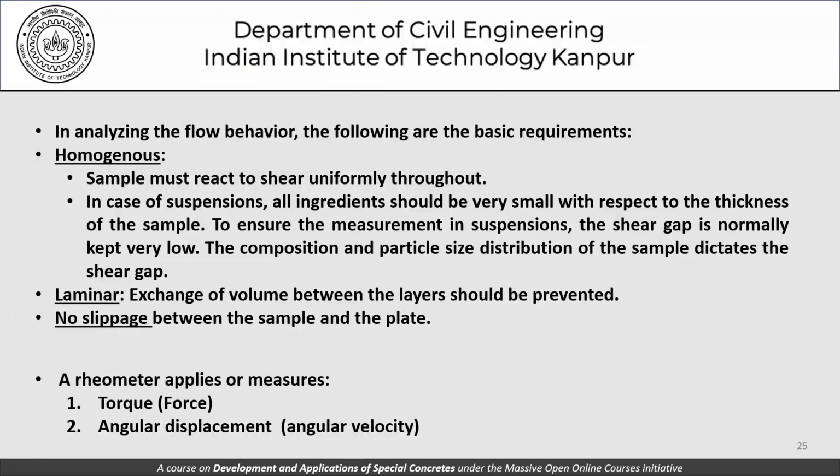In analyzing the flow behavior in concretes, or for that matter any fluid, the following are the basic requirements. One is homogeneity of the sample. The sample must be such that it shears uniformly throughout. In case of suspensions, all ingredients should be very small with respect to the thickness of the sample. To ensure the measurement in suspensions, the shear gap is normally kept very low. The composition and particle size distribution of the sample dictates the shear gap.